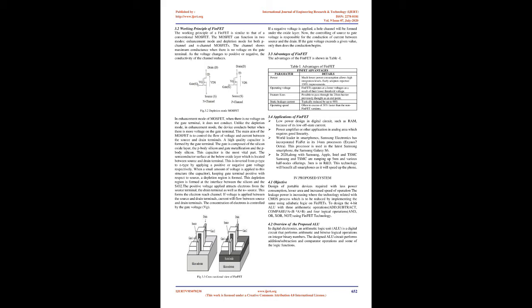Increasing leakage current does not allow further reduction of threshold voltage, which in turn prevents further supply voltage scaling for the speed improvement. Higher electric fields generated inside of the transistor worsen device reliability and increase leakage currents. Moreover, the required high channel doping causes significant challenges such as mobility degradation and random dopant induced threshold voltage fluctuations.